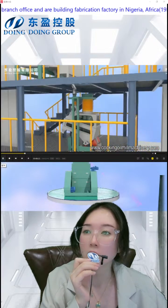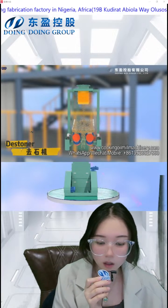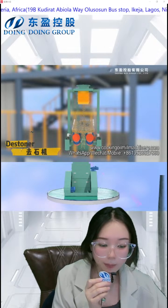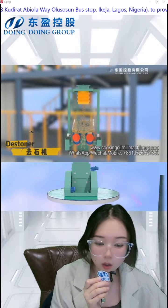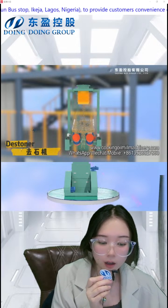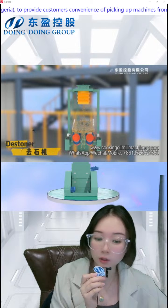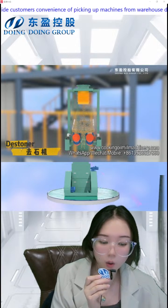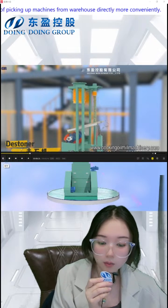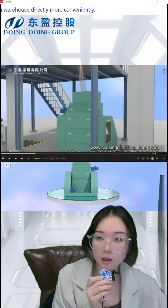And then the next machine is the destoner. The destoner, a specific gravity stone removal machine, is mainly used to remove small but relatively hard inorganic impurities such as soil and stones from the raw materials. Based on the weight of stones and raw materials, a unique steel plate and wind force are designed to remove these impurities.